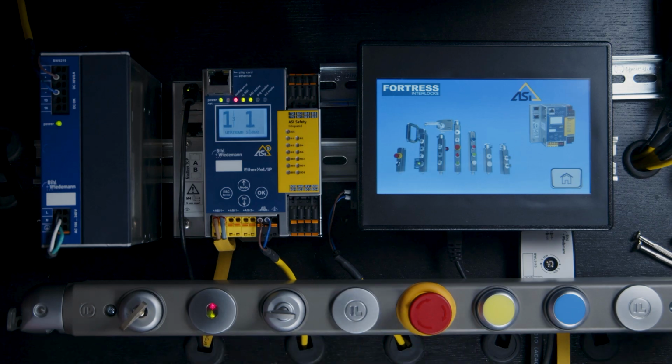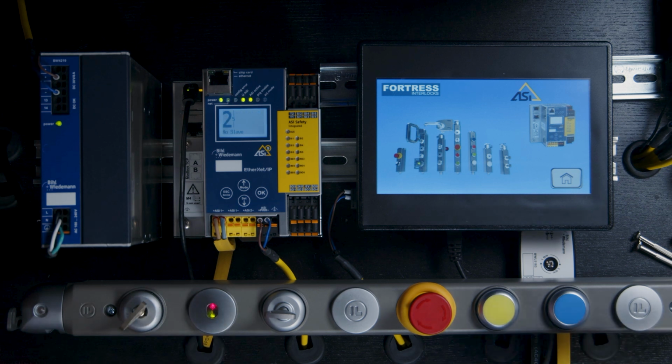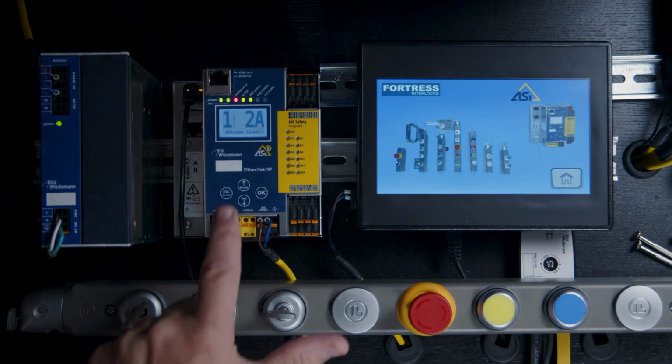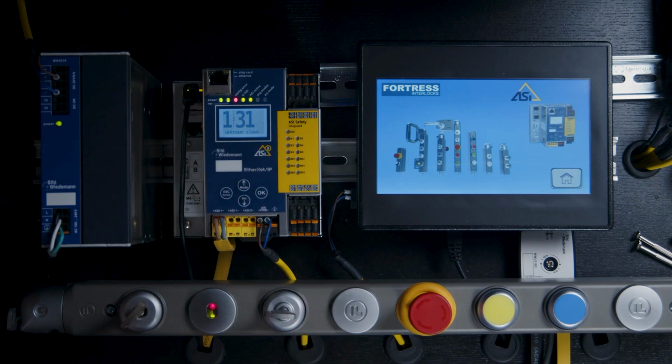Now, because those addresses start with 0, they are not legal addresses. Most ASi devices ship from the factory at 0. So we need to move those addresses up to a legal range before we can actually use the tGard on ASi. So we're going to have to use some sort of addressing tool to do that. We could use a handheld programmer, or in my case, I'm going to be using the safety monitor, which has a built-in provision for setting slave addresses.